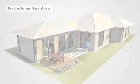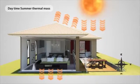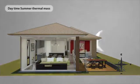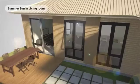The summer sun is higher in the sky, so with correctly sized and proportioned eaves and other shading devices, you can keep your home cooler by keeping the heat out. During the day, as the air inside the house warms up, it is absorbed by the slab, which is cooler because it is in contact with the cooler earth. This keeps the internal temperature cooler. At night, as the air inside the house cools, the heat from the slab moves back into the room. It's important then to have breezeways which can be used to cool the house by opening windows or doors.